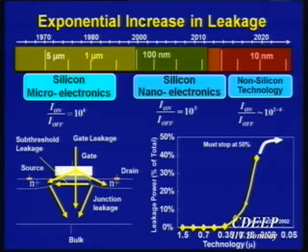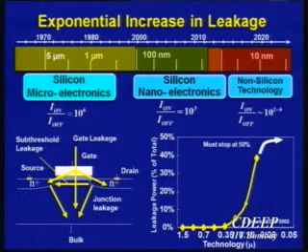One of the good ways of controlling the current, the best way to look at it, is that if you have a transistor, I'd like to control the flow of current completely, right? The gate should control the flow of current. The best way to do that is to have a very thin oxide, so you're closer to the channel, right? Because of the electrostatics, you'd like to be as close to the channel as possible, and hence control your current as much as possible through the gate voltage. Unfortunately, if you scale your oxide thickness, then of course the gate leakage current increases, and there are other short channel effects that one has to look at.